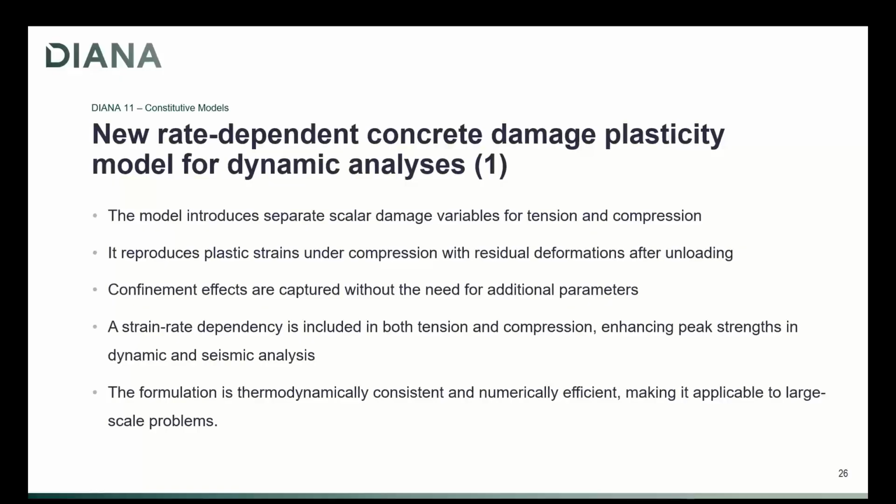It has some nice features: as the name suggests, it has scalar damage parameters, it has plasticity in the compressive part, its confinement effect is naturally incorporated in the model, and it is strain rate dependent, so it is sensitive to loading rate. The formulation is thermodynamically consistent and efficient. So this is a nice addition to Diana 11. Next slide.